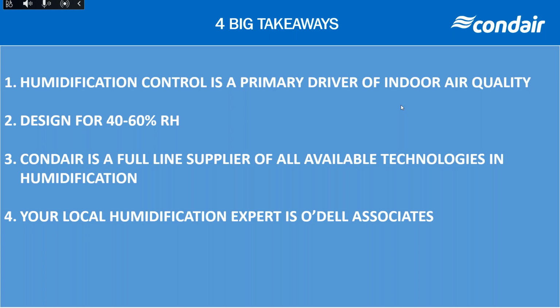for lower humidity requirements, like less than 30 pounds per hour, we're usually looking at an electric humidifier with some sort of in-duct or in-space distribution. If you're above that, between 30 and 100 to 200 pounds per hour, we're looking at a gas-style humidifier. Above that, we're looking at some sort of evaporative humidification system. But we do need to be cognizant of CSA requirements for adiabatic in hospital settings.